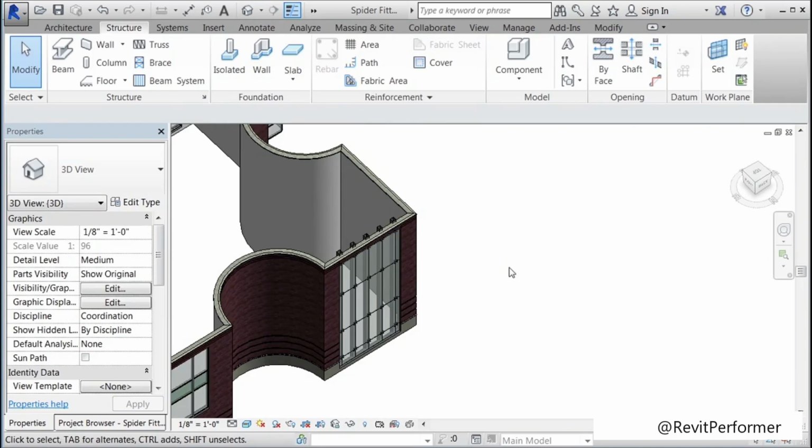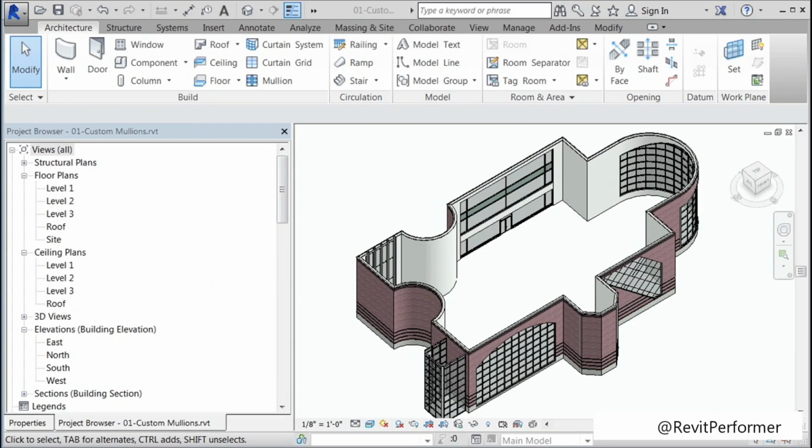So remember, if you move the curtain wall, the fittings are going to move as well, but not the framing. You can find these fittings anywhere, already modeled. I like the face-based the best because they will move with the curtain wall and are easier to install. So go ahead and use the ones that I provided with this class. This family will be a simple profile that is categorized as a mullion. We'll then load it into our project to get ready for installation.